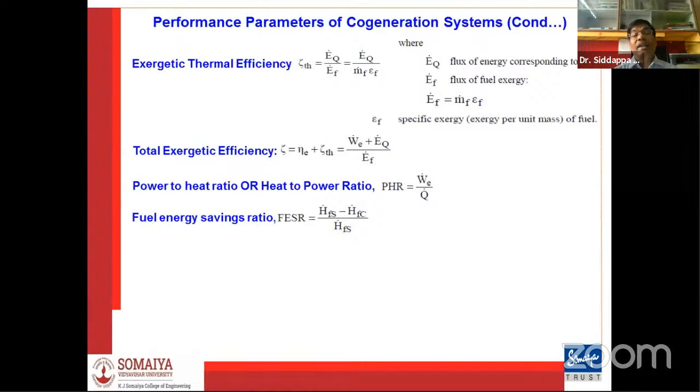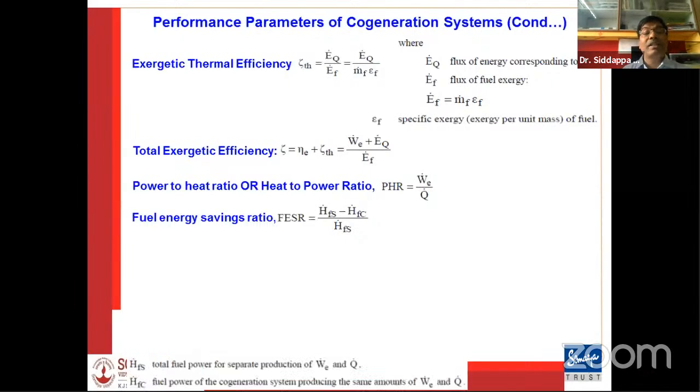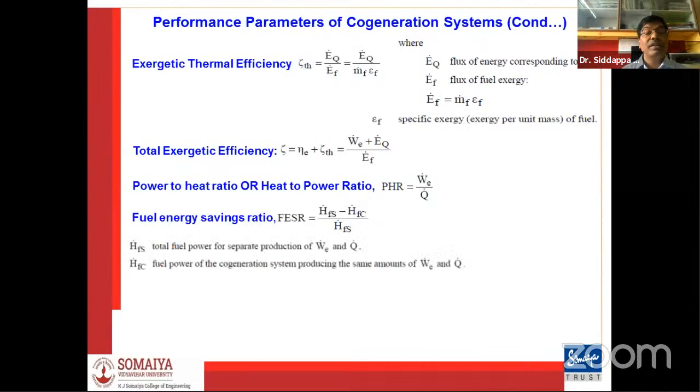And then that ratio, that means the fuel supplied using an economizer and the fuel supplied without using an economizer, will give you the energy saving ratio. It gives you how much fuel energy you are going to save to bring the temperature of water from 100 degrees centigrade to the saturation temperature. Similarly, the same concept we are going to use in all systems for calculating the fuel energy saving ratio.